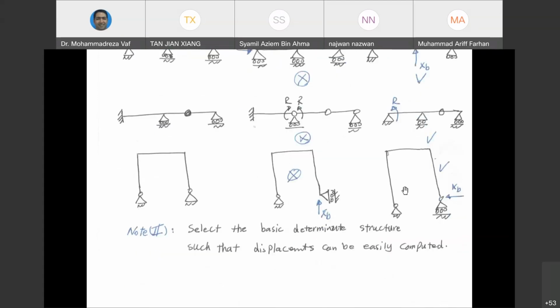Or if you have a frame, this is a frame right now, you can see, you cannot remove the vertical support reaction here and obtain that XP. Because the moment that you remove the vertical support reaction, then your structure is going to look like this one. If you apply any force from up, the frame is going to collapse. So this structure become unstable. But instead of vertical support reaction, we can assume to be the horizontal support reaction, that it is redundant.